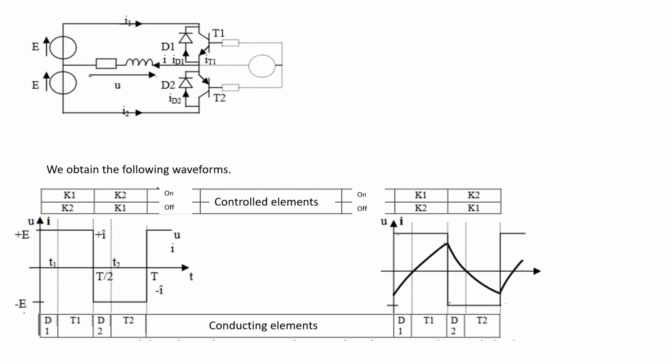The response of the current cannot reach steady state for the constant voltage, because the constant voltage is not long enough for the current to reach steady state. So when voltage changes, then the current changes again, so it always stays in transient, right? But because it repeats over time, the shape of the transient here looks like the transient here, right? This shape repeats over time, then you got a periodic steady state. Yeah, it becomes just periodic steady state. You got the point of what I'm trying to say?